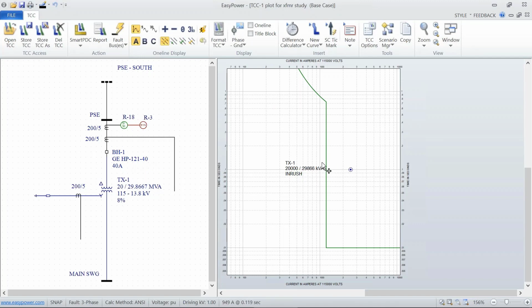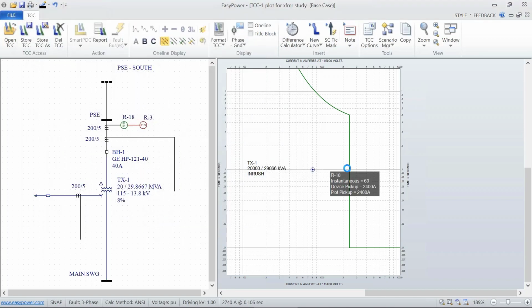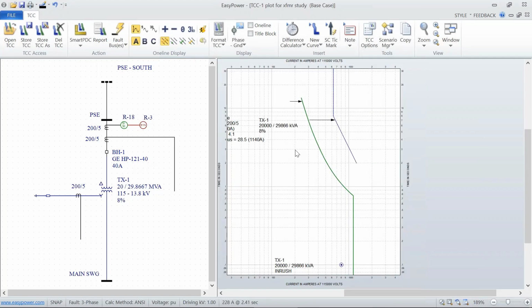So whatever standard we use and whatever the manufacturer recommends as the inrush, we want to set for, and this is at 1/10 of a second, we want to make sure our instantaneous setting is to the right of that and will not be affected by the inrush. So let's go back to what we had for 8x and go back to our 1200. All right, so the thing we haven't adjusted is the dial setting.